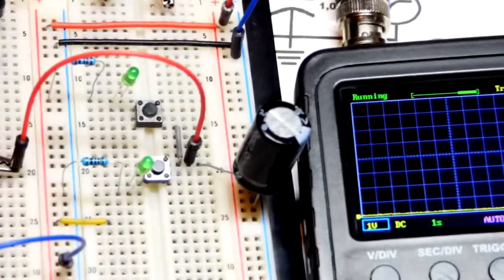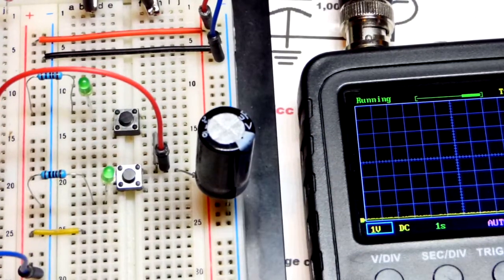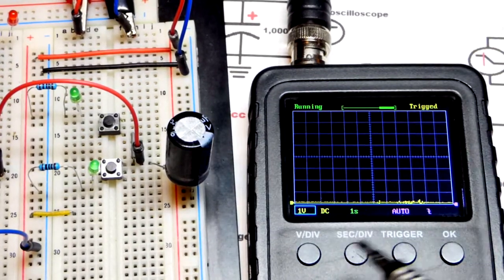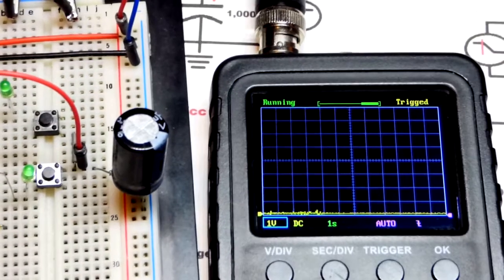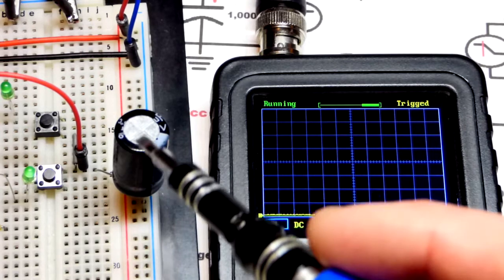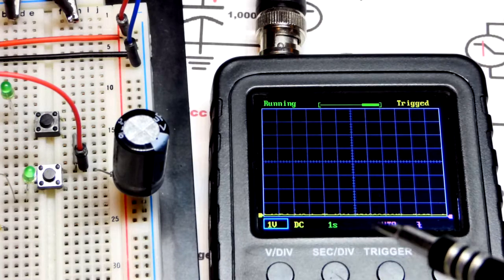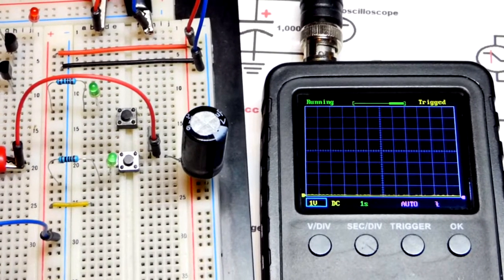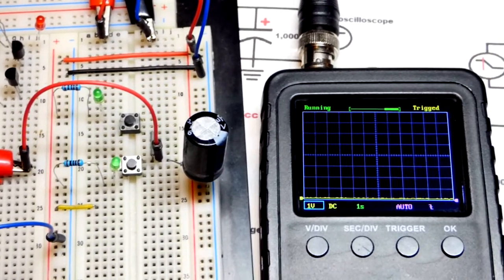So now we added a couple LEDs in series with the resistors so that we can see them light up as the capacitor charges and discharges, and we'll see a problem with that because of their voltage blocking. In any case, we're not right at 0 volts anymore, and we got some noise too that it's picking up, but that is probably because of the way these electrolytic capacitors are made, when you completely discharge them, they gain some of the voltage back naturally. They don't recharge themselves or anything, but they have a little bit of voltage.